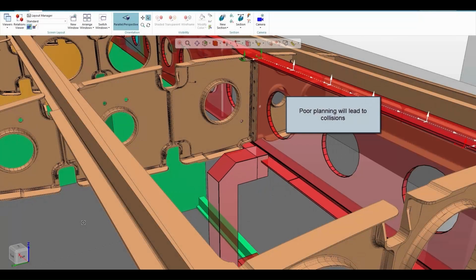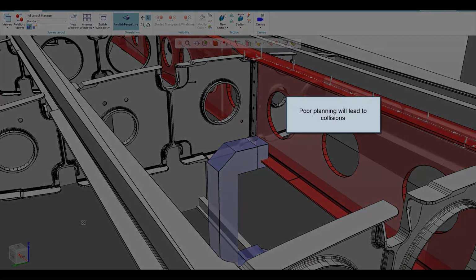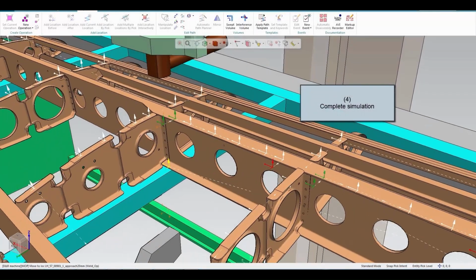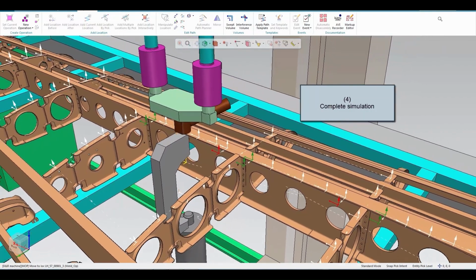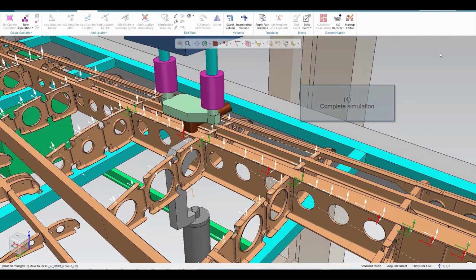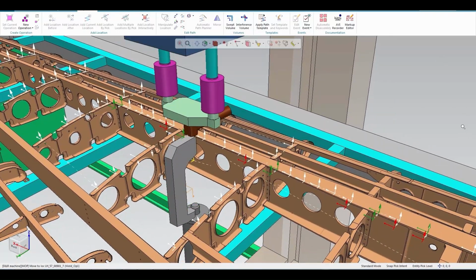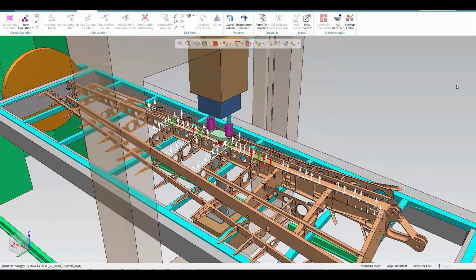For riveting operations, robots are great because they are fast and accurate in terms of the force used for each rivet, leading to less rework and scrap. Process Simulate allows the robot's movements to be visualized so that the precise placement of each rivet can be verified, and any issues will be caught ahead of real-world implementation.